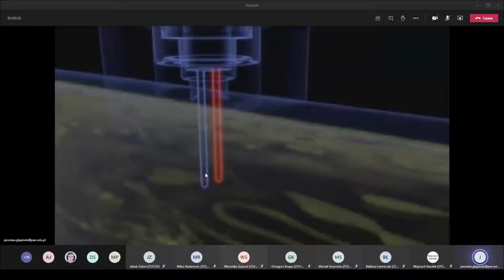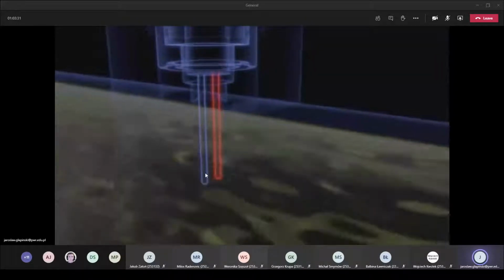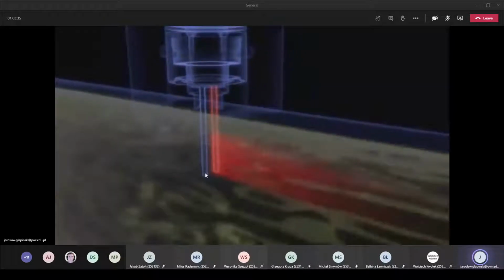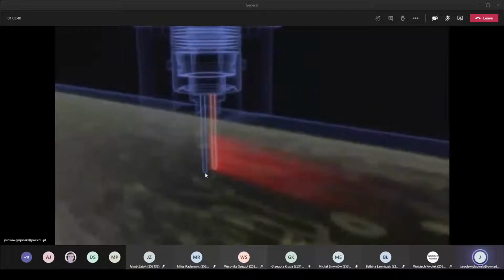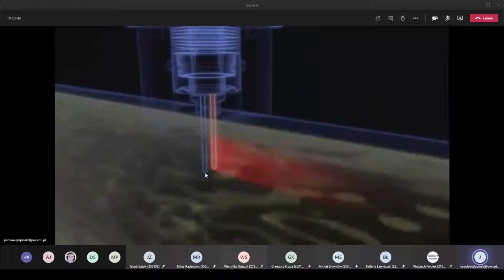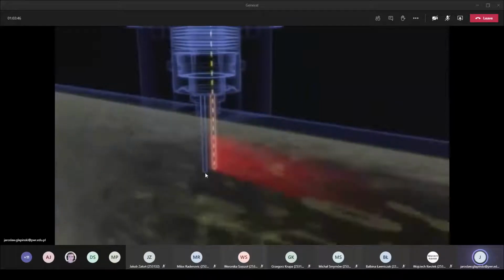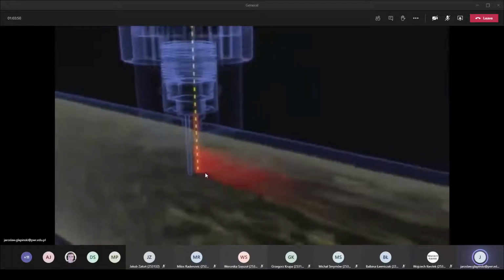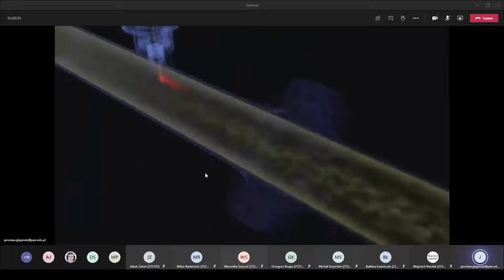If there is no flow, the differential temperature between the two sensors does not change. As soon as the fluid begins to flow in the measuring tube, heat is drawn from the heated temperature sensor via the gas flowing past. The heat then is carried off by the flow. The corresponding cooling effect is measured and compensated immediately by adding more heating current. As a result, the target temperature difference is continuously maintained.